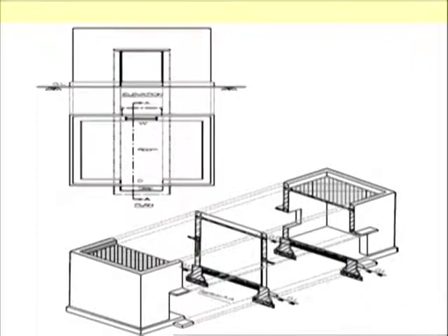If you remove this portion and you see from left to right, that will be an incorrect view, because the direction of the arrow is this direction. If the arrow direction is the opposite direction, in that case this will be the left direction. So the door will not be on this side, it will appear on this side. So the direction of the arrow is important.